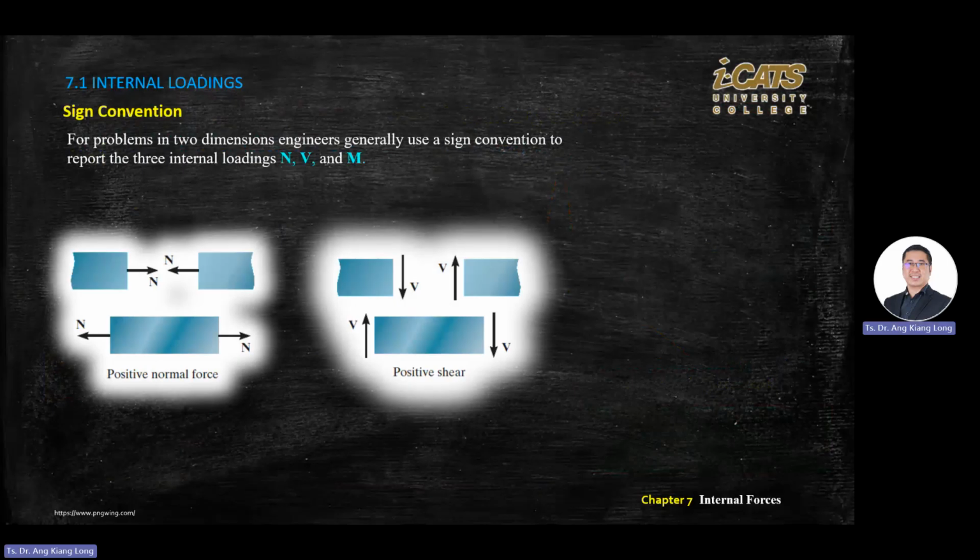You can see the difference. The top diagram is internal forces, I mean the internal section. The bottom one is actually outside. Normal forces, external surfaces. It depends on the question, whether the question asks you what and what. If you cut section one, you use the top. If the question asks you to find the shear force near the wall, then you use this one.